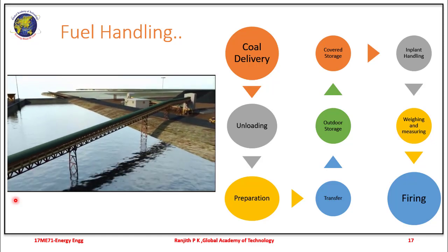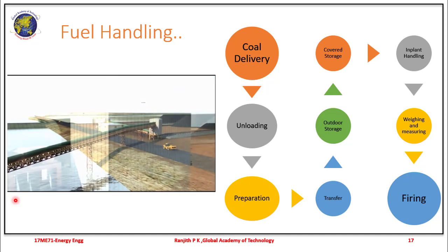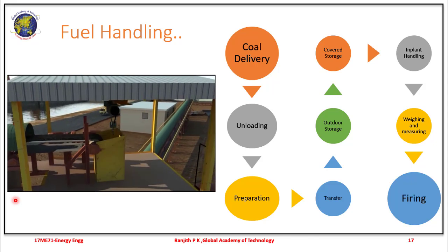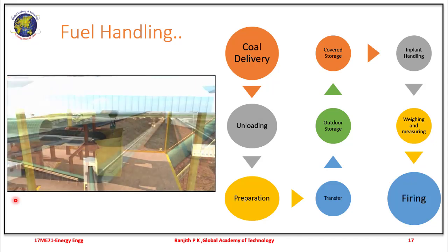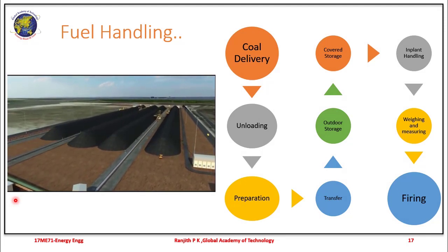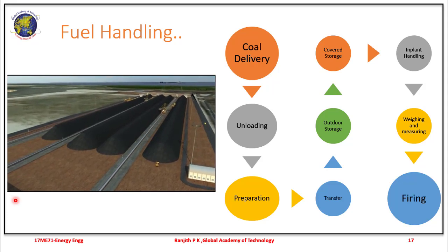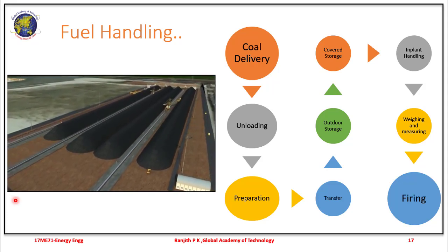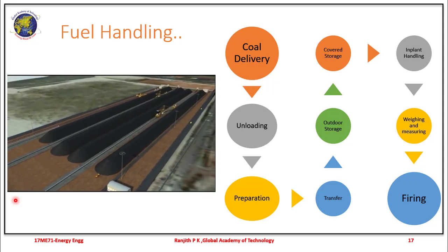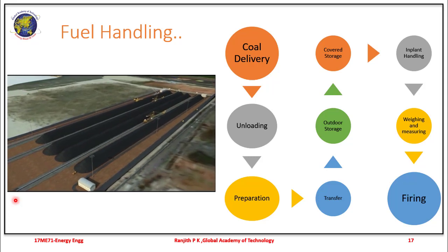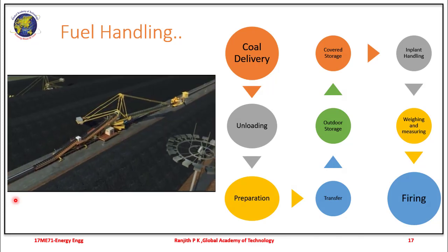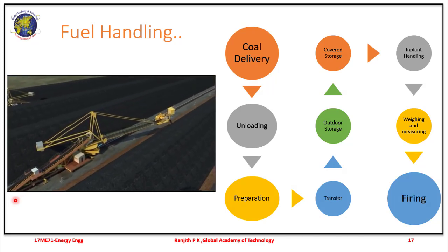When unloaded on the berth conveyor belt, the coal is conveyed all the way to the stacking area, crossing the sea on elevated galleries. All conveyor belts are well covered with canopies to minimize dust emission or material loss in the event of wind blowing. Once in the stockyard area, the material flow may be diverted into either of the two main conveyor belts in the stockyard, as selected by the operator of the terminal. The stockyard has a maximum capacity of 1,100,000 square meters, of which 220,000 square meters are assigned to blending operations that vary depending on the requirements of the end customer.